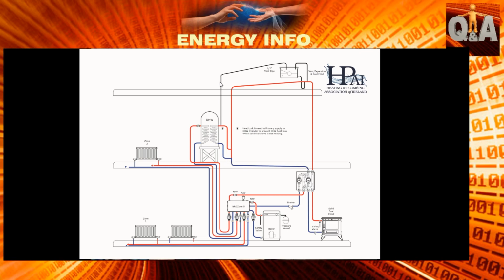The actual expansion of the system is a critical part of solid fuel, and that's the 3/4 or 1 inch expansion over at the top, Bill, is it? Right hand side, over next to the expansion. On that note, lads, if there was a solar system in place, this is a potential fix, because if the solar was done below here and it was heating the tank, it can't get back out. It literally cannot get back out. So you've created what's called a heat lock, and it stops the problem with heat drifting back around the attic.